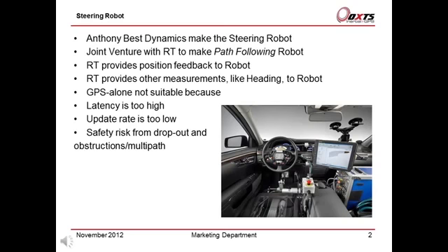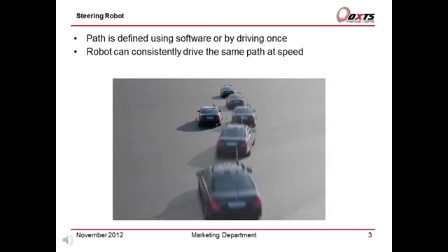Also, GPS alone cannot be used because if it was to drop out, the vehicle could not steer. Using an inertial system, the dropouts in the GPS do not matter as much. The robot can hand over the operation if the inertial solution becomes too inaccurate.